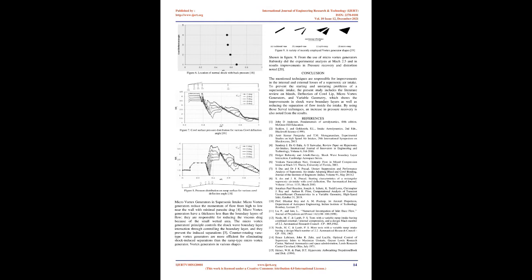Providing bleed slots inside the intake is an excellent way to prevent losses. Location, design, and proper sizing are necessary to achieve the engine's efficient performance. Bleed slots are provided at those locations where the shock is going to be attached as per design, which converts the weak shock to a strong shock due to the reduction in the shock wave boundary layer. Bleeds suppress the shock wave's boundary layer. Possible locations of bleeds are on ramps, cowl lips, and at the sidewall.